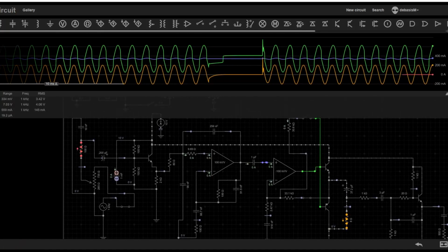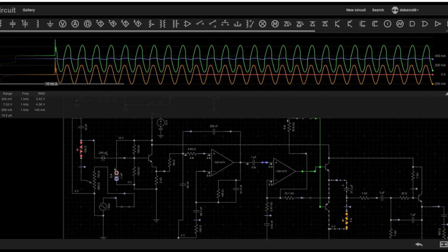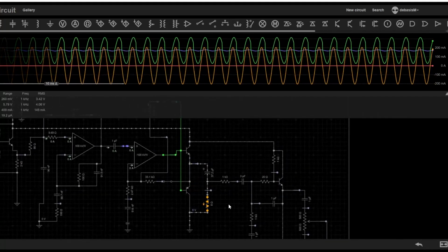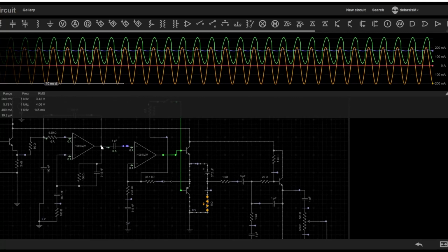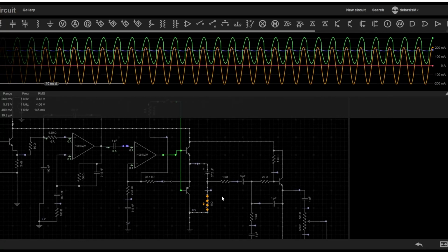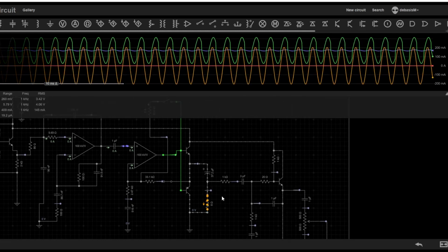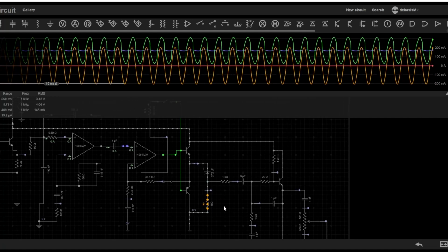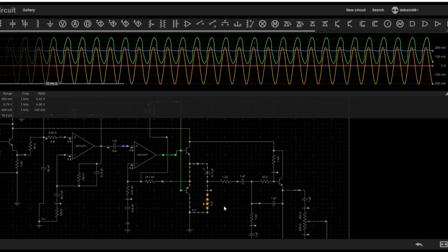Let's see how much current we're drawing. You see, it's literally zero. It's some microamperes, 9.62 microamperes we are drawing from the audio pin, and here we are generating around 200 milliamp of current. We are giving some random values of the resistor and capacitor, not so precise, but you can imagine what is happening here. You draw some microamperes from the audio pin and provide some 200 milliamp of current to the speaker. So that's the role of that audio amplifier.